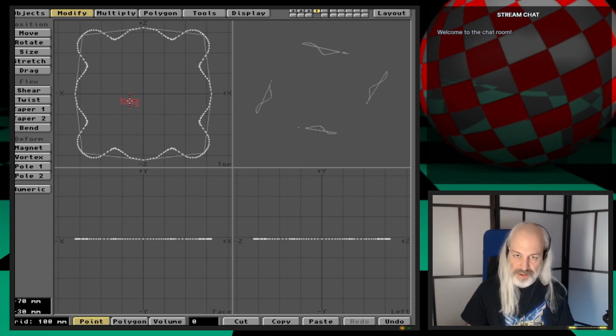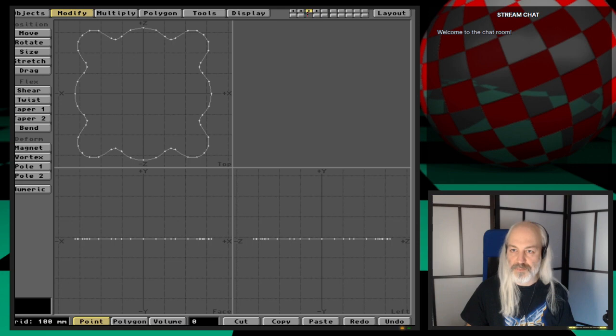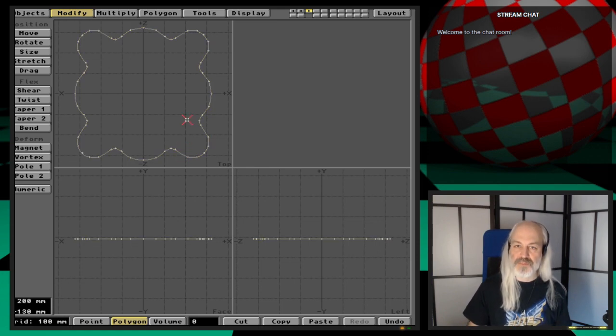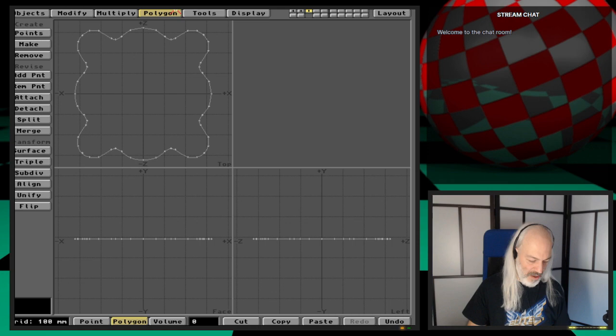I forgot what I forgot to do here is this is a multitude of curves. See, there are many curves. It's not one, so I want one closed curve. So let me see if I can merge. Yeah, I have one curve here. Amazing. So I just pressed Shift Z, which is merge, polygon, revise, merge.